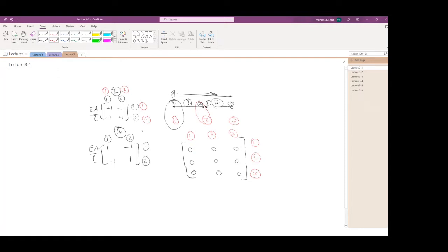If you look into the second element, the first node is connected to node number 2. And the second one is connected to node number 3. So it is 2, 3, and 2, 3. Now the assembly of the system is just reduced to reading coordinates and adding them into the system.